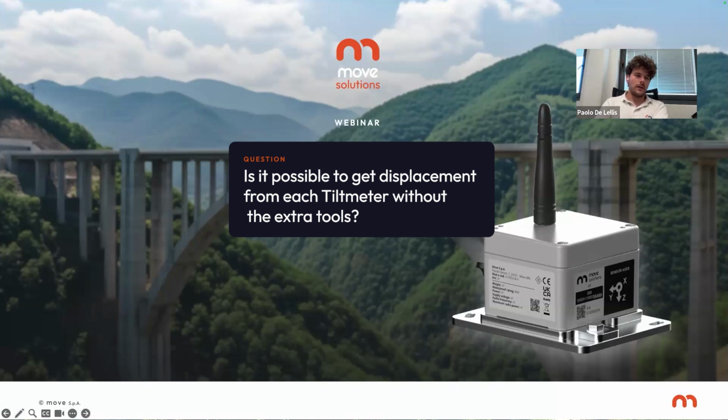But another unit that you can select in the preferences is, for example, millimeter per meter. Millimeter per meter is another way to see the angle rotation with a value more familiar for displacement, because you start from degrees or you obtain millimeter per meter, but it's the same way to describe rotation.